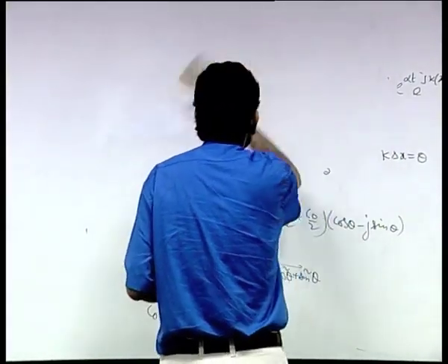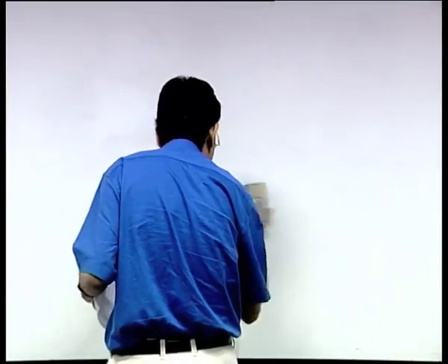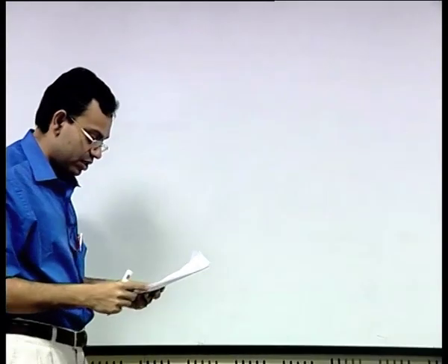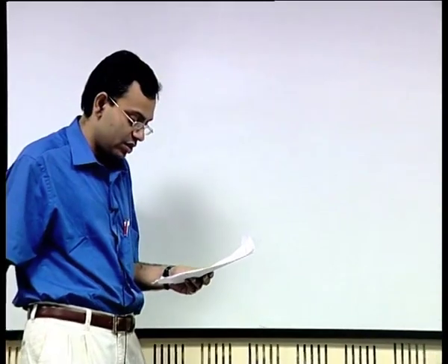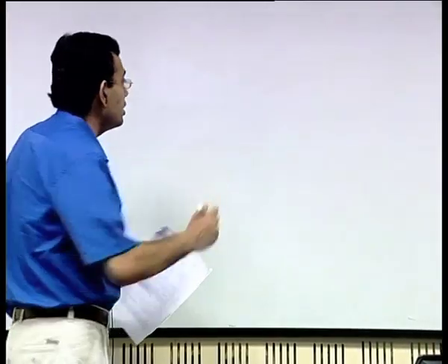The next question is, consider a one dimensional steady state convection diffusion problem without any source term. Derive a profile assumption for variation of the dependent variable. I am repeating, derive a profile assumption for variation of the dependent variable in the advection term following the QUICK scheme.